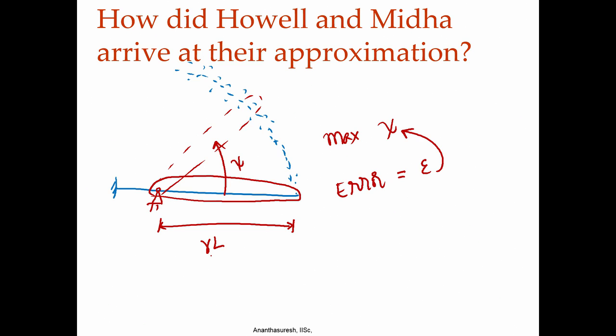Based on that they came up with these values of gamma, and at the same time they also came up with the values of kappa, because kappa again they would try to see, if it goes there then the moment here has to be equal to kappa times the angle psi. The moment of course comes from the force, that component as well as this component; you can take moment about this and put that there, and that should be equal to k times psi.